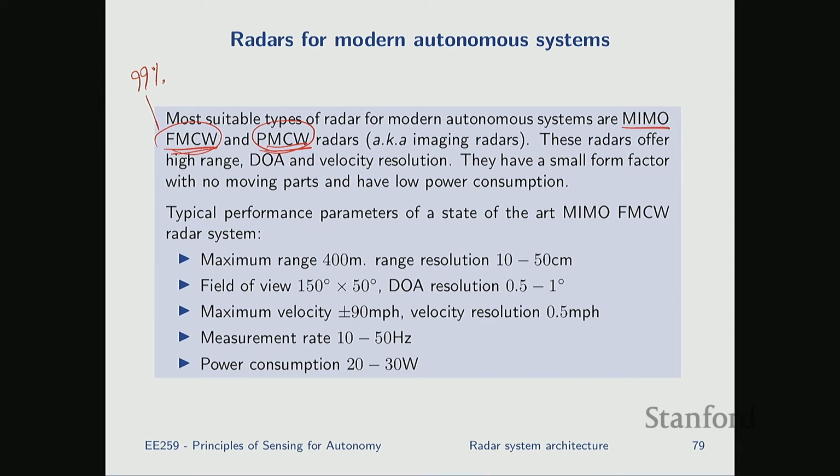I'm sure in a few years you would see more and more PMCW systems, but today there's not that many of them. There's one company I know of in Texas called Under that builds basically PMCW systems, and they don't sell them to the general public. They just have exclusive contracts with some customers. But for FMCW, there's many companies, and you can buy either full systems from them or just transceivers and design your own antennas. So because of that, we will focus mostly on FMCW.